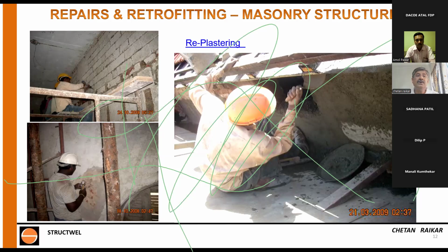So it is extremely important to abrade and bring out the redness of the stone. Remove that top micron layer. This layer must be a few microns, maybe 50 micron, 100 micron, nobody knows. So just remove it with a light wire brush. The abrasion should not be so heavy that the brickwork is damaged, the bricks are damaged, in brick masonry.